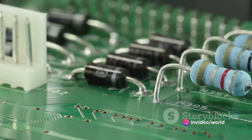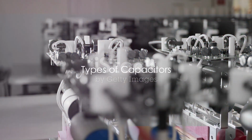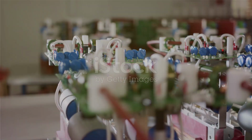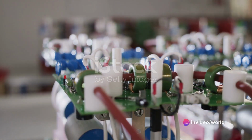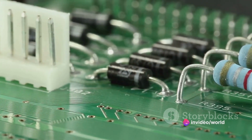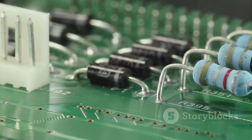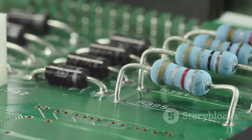But there's more to it, isn't there? Different types of capacitors, perhaps? Indeed, capacitors come in multiple types, each with unique properties and applications. First up, we have electrolytic capacitors. Known for their high capacitance, they are often used in power supply filters. However, they do have a downside. They're polarized, which means they can only be connected one way.